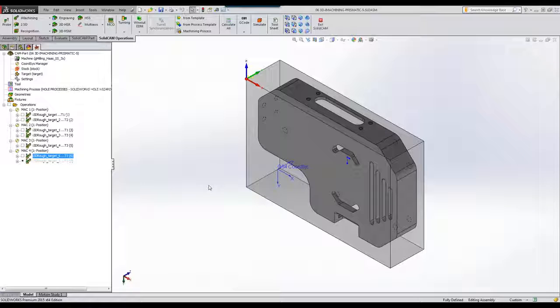So what we've basically done here with all these parts is we've showed you how easy it is to work with iMachining 3D on prismatic parts. Now, again, you can do it with iMachining 2D, no problem. It'll work out very well for you. Well, when you make complex parts, when you have many different pockets, many different depths, or very deep parts, as I showed you in the very beginning, it pays to use iMachining 3D because that will cut down on your programming time, and in certain cases, like I showed you in the first case, it even cut down your machining time because it was able to go where the previous operation type, iMachining 2D, was not able to go, and that was checked automatically.